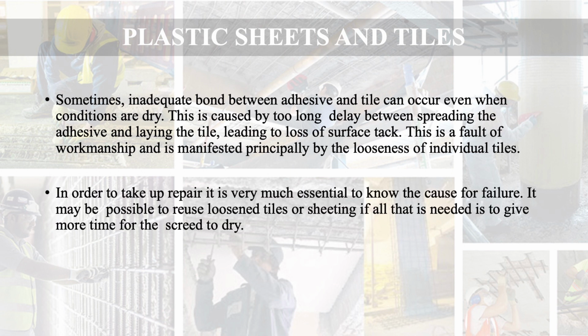In order to take up repair, it is very much essential to know the cause of the failure, because if you do not know the cause of the failure, you can't do the proper repair. It may be possible to reuse loosened tiles or sheeting if all that is needed is to give more time for the screed to dry.